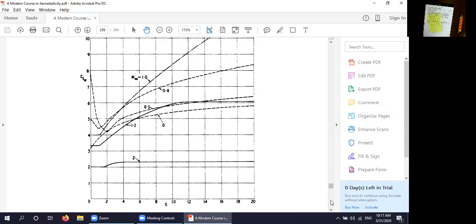And I said, yes, we're computing both because we've taken the equivalent alpha, the equivalent angle of attack, which is this dH dt divided by u infinity, and set it equal to 1. So whether it's CL or CL over alpha, since alpha is 1, it's the same thing. So this plots CL alpha, or CL divided by alpha, where the alpha is 1, versus S.